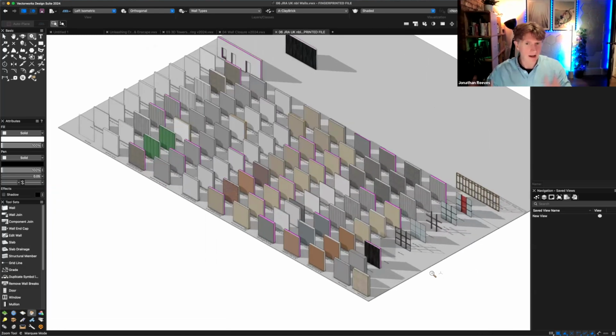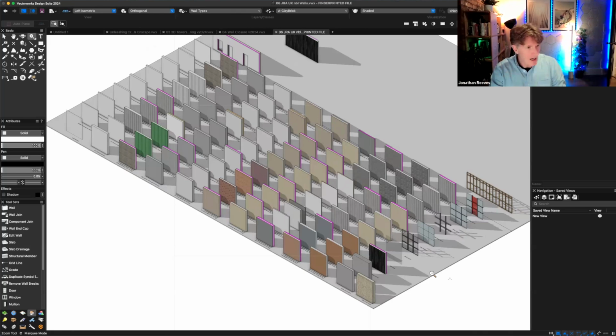I like to have visual libraries where I can go and select the wall type, copy them, and bring them into the file. And what I encourage practices to do is set up their own wall types per project, and you can then reference those into multiple projects. So if the wall type changes, it can update potentially 10 different documents very easily by having a centralized project library.